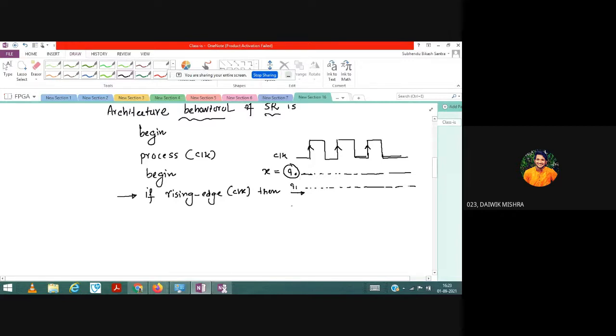And Q2 will depend upon the Q1 output. If you draw it carefully, let us say the Q0 value is 1 for that particular event. Then Q1 will be high in this particular clock event. It is just moving in this direction, and Q2 will obey the third clock and follow this output.